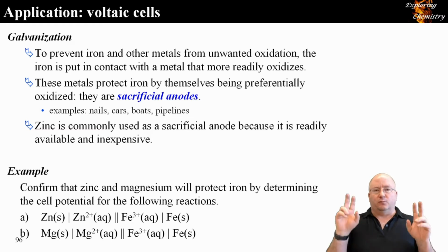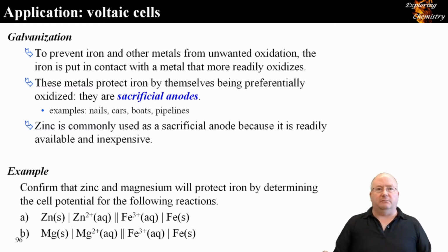In those areas, the rust protection on your vehicle is often reduced. If you buy a vehicle, in many jurisdictions they offer you a 5 or 7 year rust-free guarantee, because the galvanization on the iron body of your vehicle is sufficiently thick that under normal conditions it will last 5-7 years before all of the zinc is used up and it starts rusting away the metal. In cities like Toronto, Edmonton, Calgary, and I think Vancouver still does it, I'm not sure, they have either reduced that rust-free guarantee or eliminated it completely because of the amount of salt that is thrown on the roads.